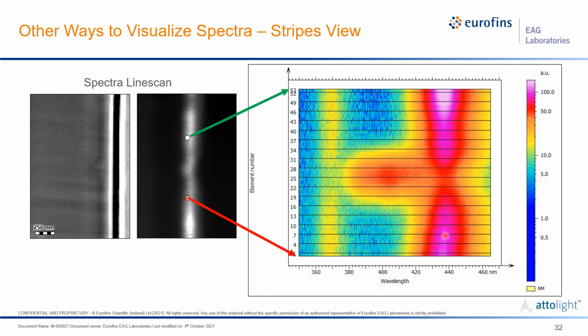high intensity of emission around 440, 439. But as we go into the V defect itself, the emission intensity lowers, but also blue shifts greatly, right? So now we're getting primary intensity around 400 nanometers, 396 or so. So this is just another way we can look at features within our sample and try to understand how the emission is changing relative to the sample itself.